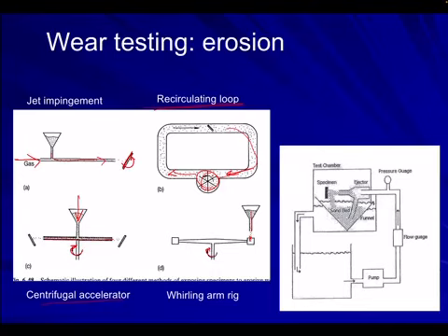You could also, in terms of the slurry, have your specimen here, you pump your water, measure the flow rate, and that is blasted onto the sample, but it then gets the sand into that, and you measure the erosion of that particle.